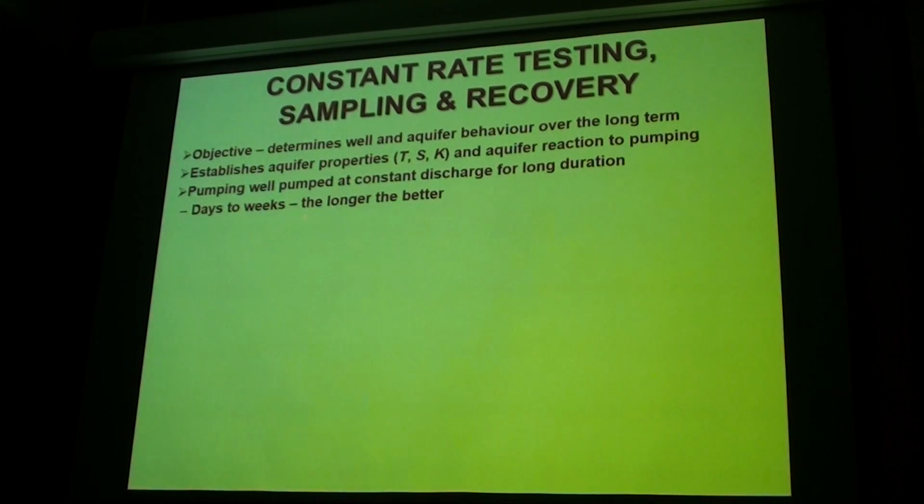The longer the better. Okay, if you can do 2 or 3 good pump tests, that's awesome. Again, sometimes the cost doesn't allow that. Okay, but you certainly want days, but preferably weeks. Okay, the longer the better. It's really good if you do that.